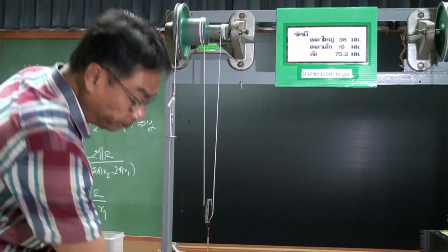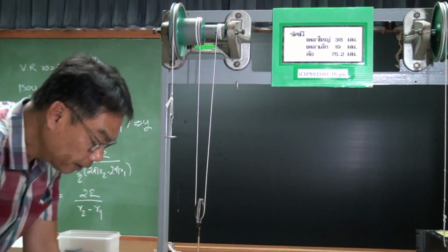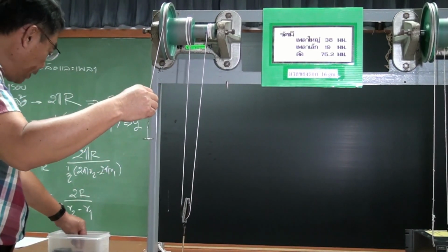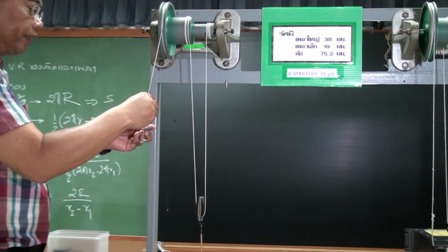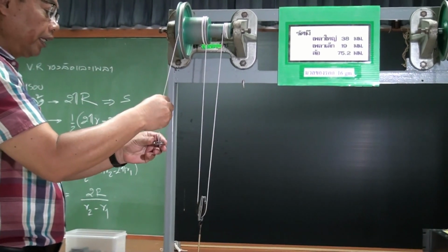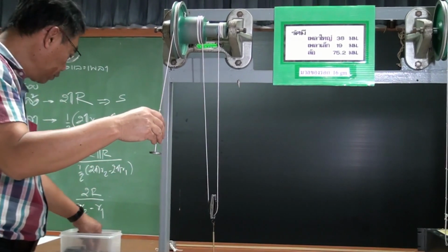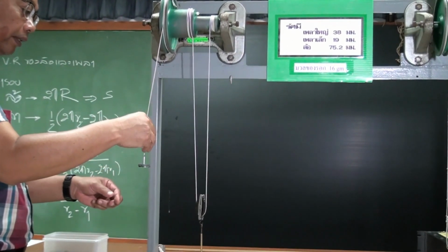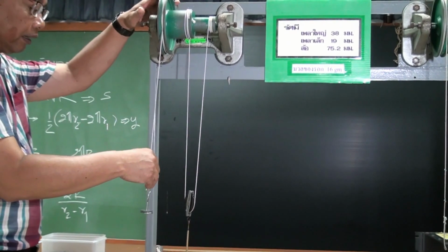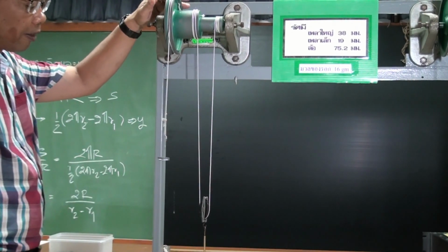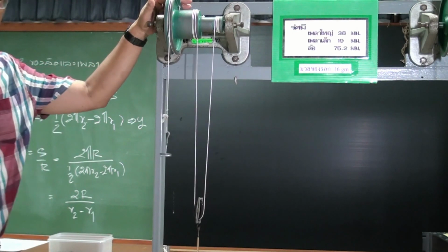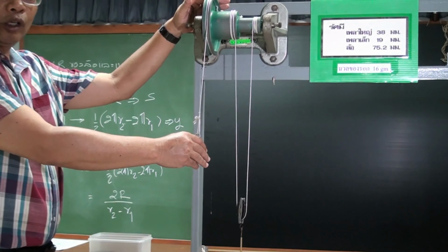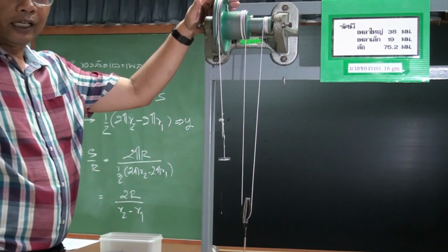And as you can see, as you move the mass on the left, which is the F, it's going to move a lot, but the mass on the right, which is W, is going to move very, very little. So first of all, before doing any measurement, be sure to calculate the velocity ratio and then slowly add the mass. If you add too much or too little mass, it's going to start moving by itself. So again, tap it and try to achieve the kinetic equilibrium in order to proceed with this lab.